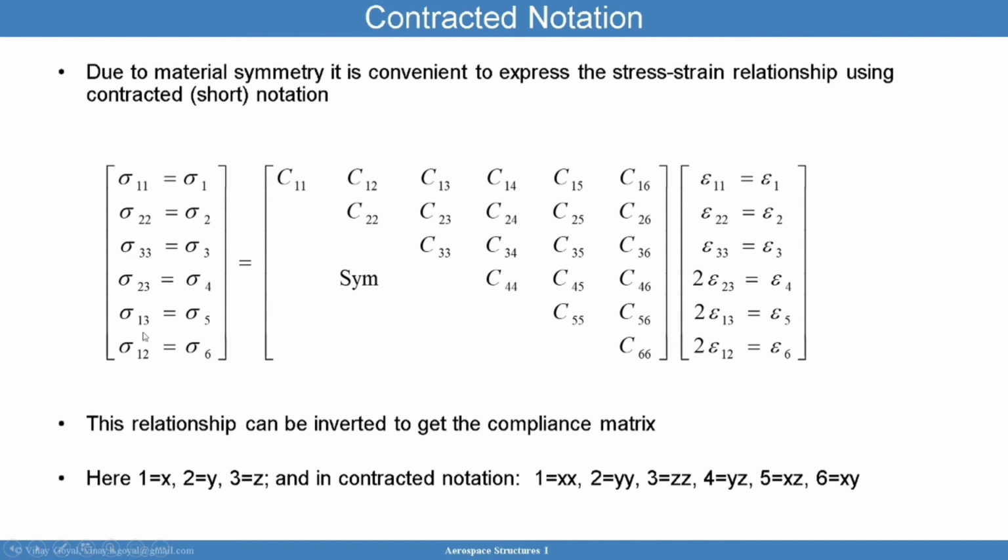These are the 6 stresses we talked about. The first 3 on either side correspond to the normal quantities, while the bottom 3 are the off-diagonal quantities, and they correspond to the shear behavior of the structure. Due to material symmetry, we're going to just say that this is symmetric.